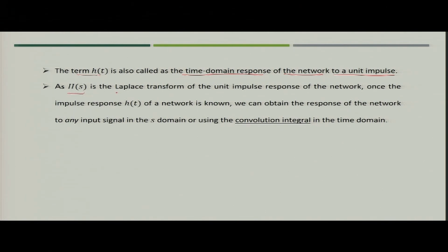Now, as H(s) is the Laplace transform of the unit impulse response of the network, once the impulse response h(t) of the network is known, that means we know the response of the circuit when a unit impulse input is provided, then we can obtain the response of the network to any input signal using the convolution integral in the time domain or the corresponding S domain analysis.